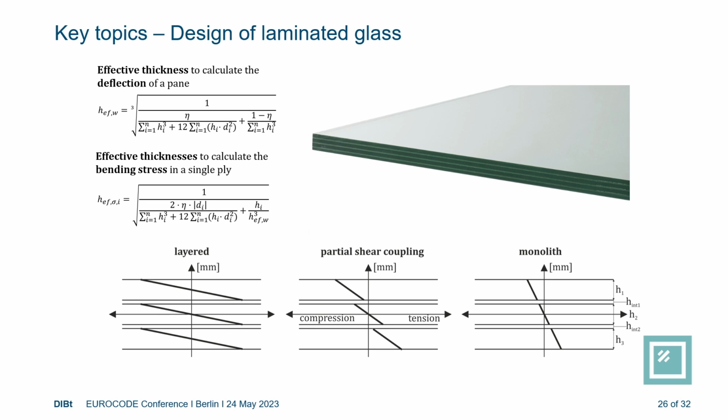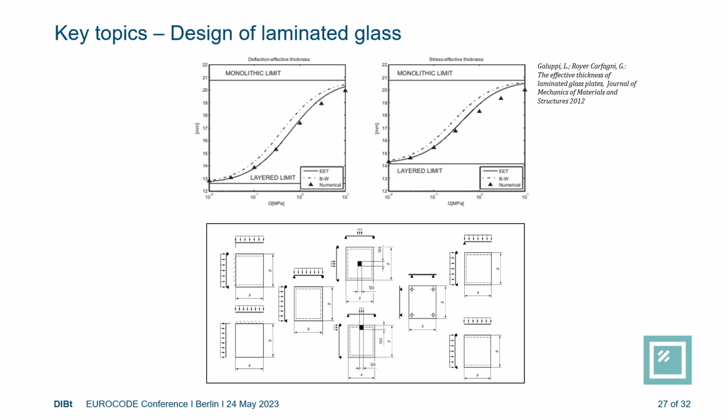And all of these states you can consider with these kinds of formula, which have been developed for all kinds of plates, shapes, loadings, points, line loads, distributed load, and so on. And also depending on the temperature you have, for instance, coming from the sun. And that we have then included into a model, which we have here in this code. And you can see that these are a very good approximation to finite element simulations and so on.